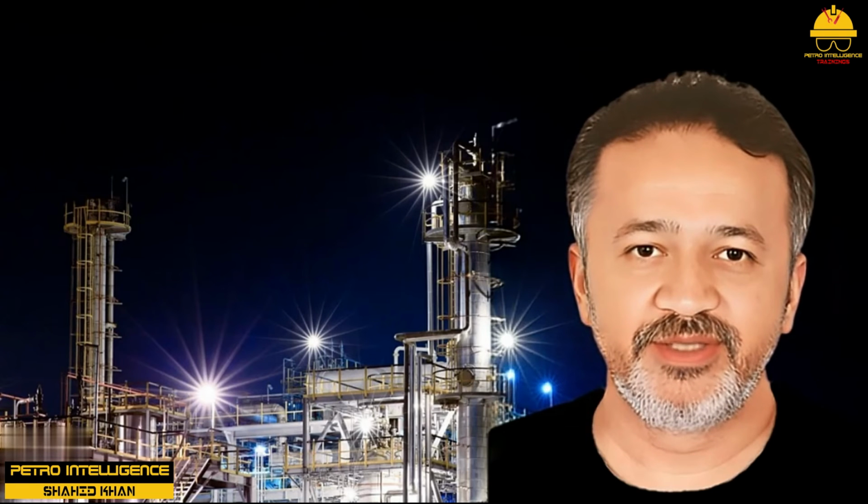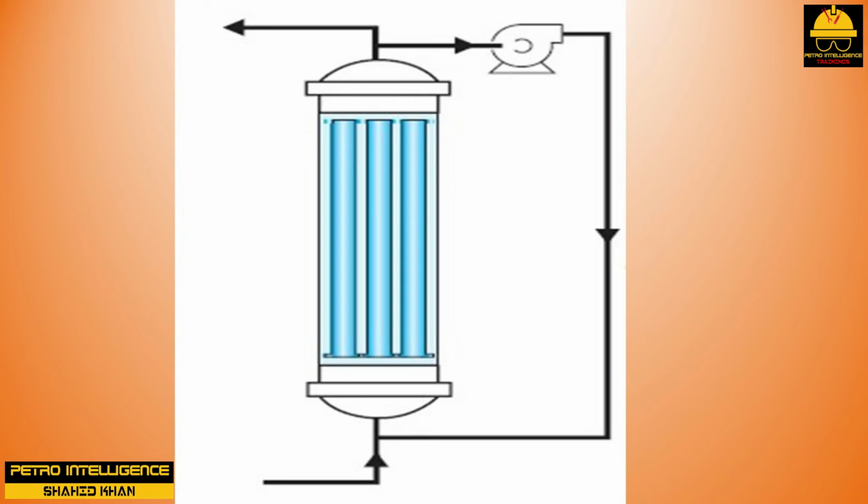Tubular reactors. The design of a tubular reactor can vary from the simple jacketed tube to multi-pass shell and tube reactors. This type of reactor is simply a heat exchanger in which a reaction takes place. Tubular reactors are used for liquid and gaseous reactions. The raw material feed usually must be fairly clean, or it may plug the tubes.